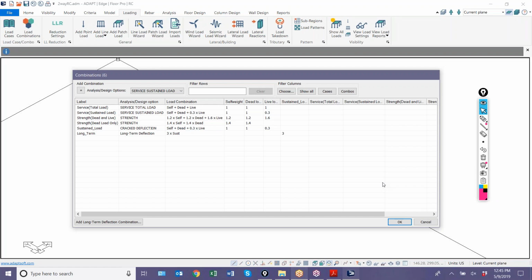So in your case, you would have to run the model with only gravity level combinations, for example, determine the amount of rebar, and then without gravity and with lateral and determine the rebar. It would have to be run twice. We do have a request to actually be able to merge designs from two different sets of runs, so we can basically envelope all rebar from different analysis runs. Or we would actually tie it to usage case. So usage case 1, you would actually be able to define a set of combinations. Usage case 2, another set, and then we would merge them in the results in terms of the rebar output. And also, I guess, for stress checks in this case.